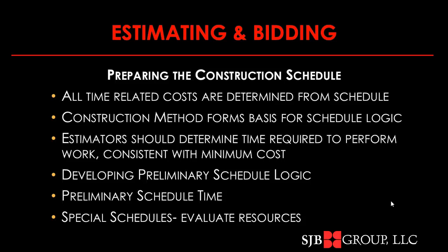Some of the special schedules we might look at. One would be a labor loaded schedule, which is ideally you want to develop your labor resources slowly and build up to the middle of the project and then slowly ramp those down. Your first look at a schedule with the labor loading on there may indicate you need to adjust your schedule to improve the ramping up and down of labor.